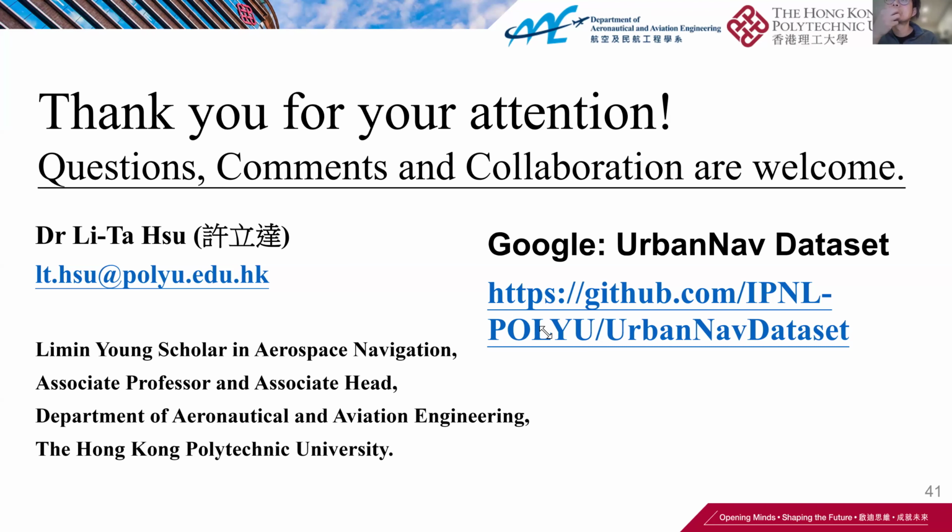Dr. Xu, what 3D building models were used to generate the sky mask, and what's the accuracy of the model? Okay, this is a great question. The 3D model we use is actually maintained by the local government, the land department of the local government. They have the street view car, they have the aerial image. They also do their own optimization, fusing to come up with this 3D building model, which is widely available for public use. And the accuracy, horizontal and vertical, they claim is about 1 meter. That's the 3D building model I use. Yep, that's the first question.